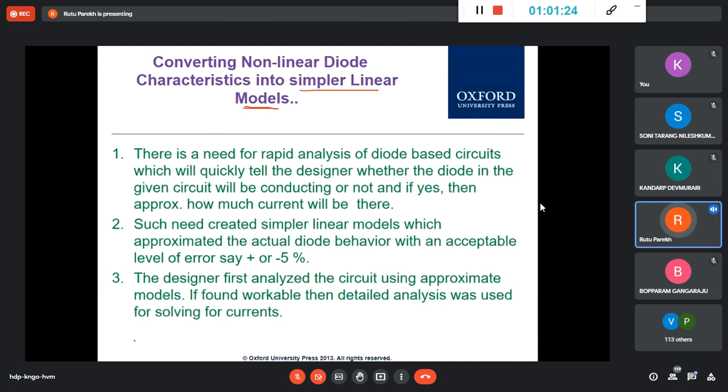Now, to do all this pen and paper work or simulation work, you need a set of equations. Pen and paper is okay as an engineer's first step, but if this is one diode and there are like 100 diodes in a circuit, or too many components, you have to simulate. Your computer doesn't know what a diode is; it knows the IV equation. So every component has a set of equations, and that set of equations is known as a model.